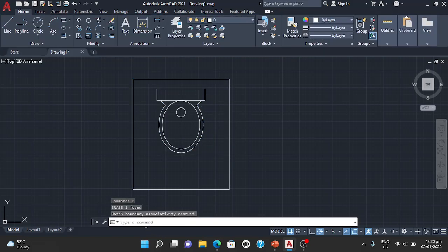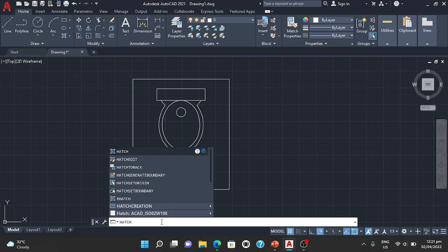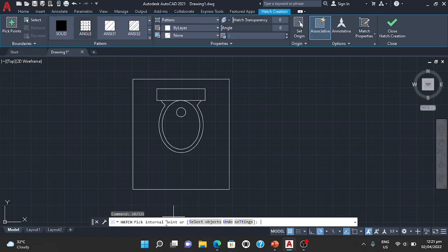Okay. So let's try to type fill. Automatically our fill is set to on. Based on this, fill is active, fill is on, so we could use hatch. So what if we try to turn it off? Try typing OFF, turn it off. So we have here fill is turned off. Now let's try to type again hatch. By typing hatch and clicking enter, automatically select objects.